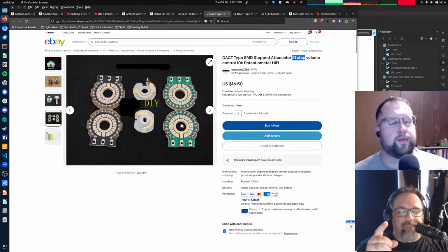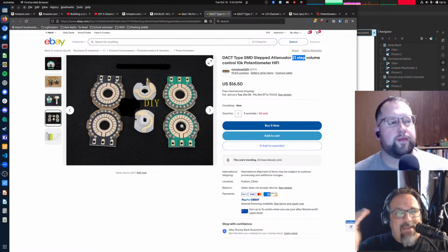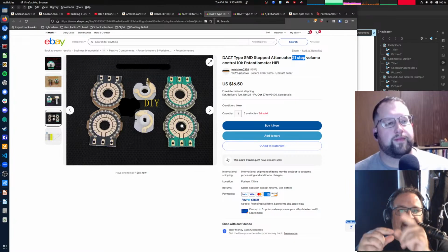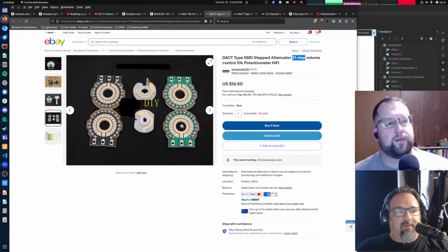The other thing that is more important in an audiophile environment is that because these are very precise resistors, usually 0.1%, the matching between the left and right channels is incredibly tight. That is also hard to do with an analog potentiometer, because analog potentiometers are literally a goo that they just wipe across the surface, and if the goo is a little bit thicker here and a little bit thinner there, then the line of resistance to knob turn may not be perfectly linear.